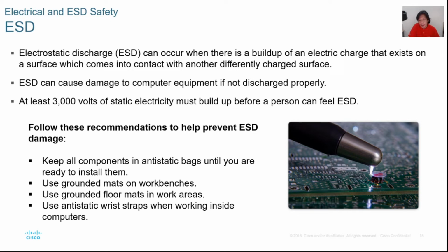Use ground mats or workbenches. We will be demonstrating some of those when we reach the assembly and disassembly. Use grounded floor mats in the work area, especially if you're going to conduct disassembly and assembly of your computer components. So it's much better to have grounded floor mats. And use anti-static wrist straps.